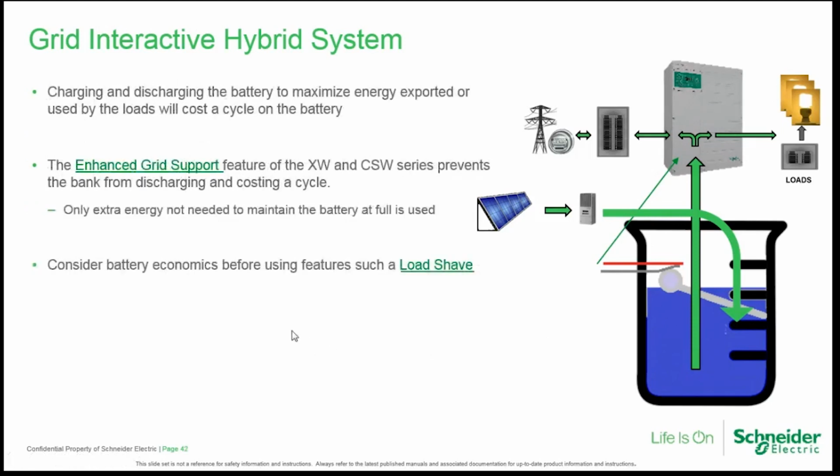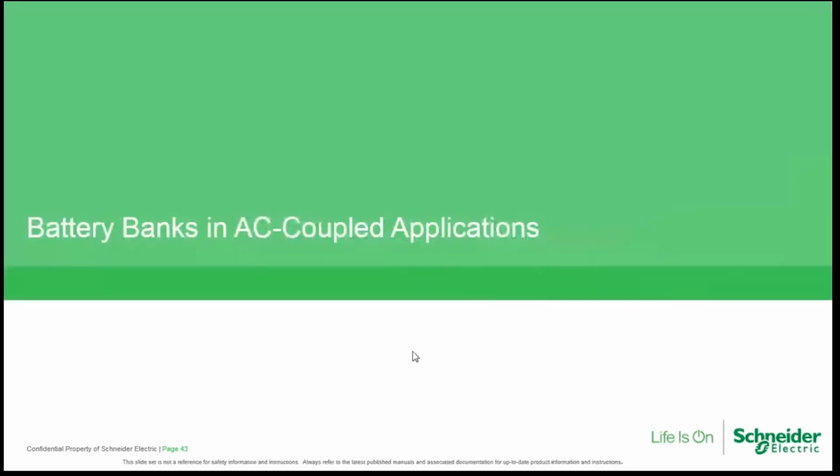And you also want to consider your battery economics before using a feature like load shave. That's the feature where it allows you to dig into the battery, discharge the battery in the evening, charge it during the day. Sometimes it makes it worth it, but if we look at the math that we did earlier, you have to do the math yourself.